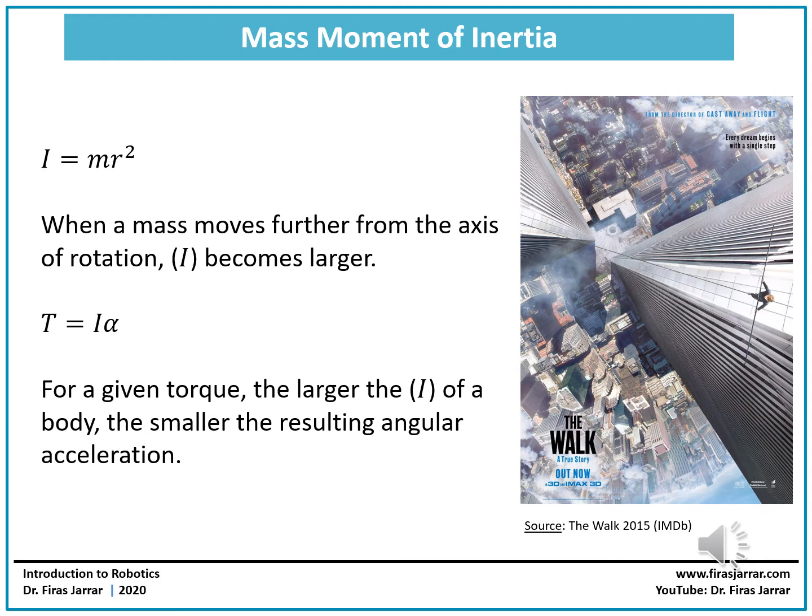By just looking at the simple formula for a point mass, where the mass moment of inertia is defined as mr squared, you can see that this horizontal pole would really increase the mass moment of inertia of this high wire artist about his own vertical axis, because the pole is heavy by itself, and it's far away.